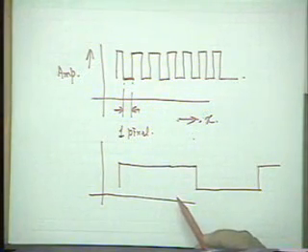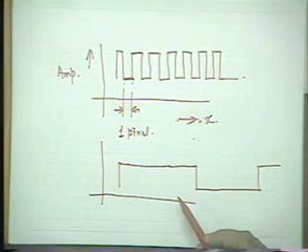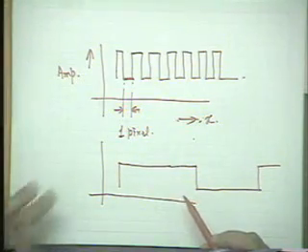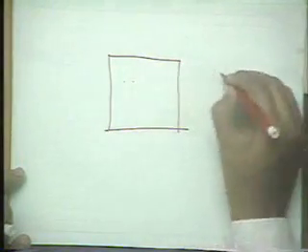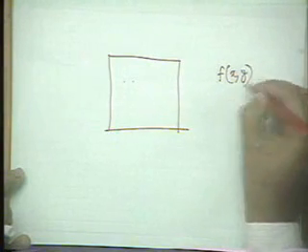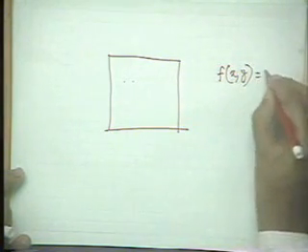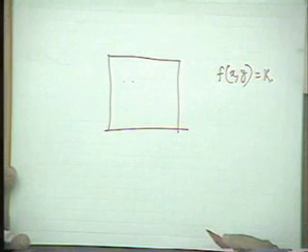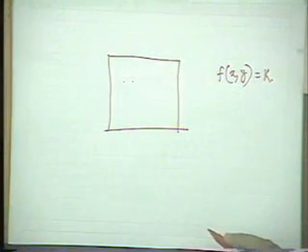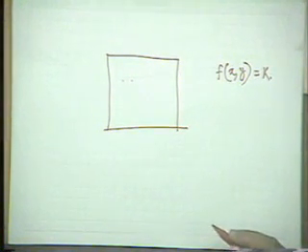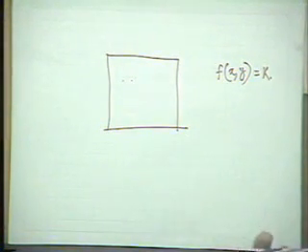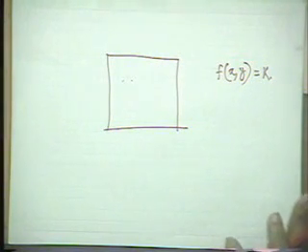In the extreme, if an image contains an absolutely uniform and constant brightness region, where at all points the image function f of x,y is equal to some constant k, then very clearly that image has only the DC component, or only the zero frequency component exists.